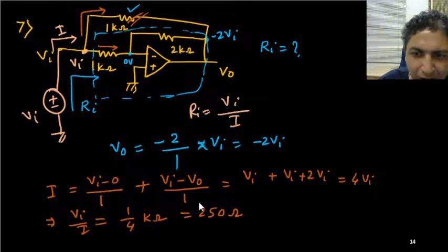If you find one pole at origin, it is obviously a conditionally stable or marginally stable circuit. So if you apply signals other than DC signal, this circuit will show bounded output. It will be unstable if you apply DC input. It will go on increasing or decreasing, going towards infinity.